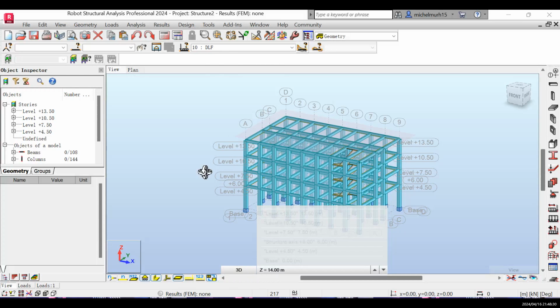In this video, we'll talk about live loads. The live loads in this structure, especially between the floor and the roof, include the weight of people, the furniture, the temporary movable items. These loads are dynamic, so they can vary depending on occupancy and also depending on the space. I'm going to show you how to apply the live load to this entire structure.